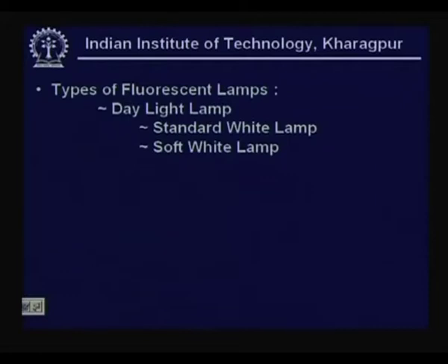Now, with this in mind, we have the fluorescent lamps which are quite often used, enabled by the utilization of mercury vapor discharge, which had a low utilization factor compared to sodium vapor but good color rendering, and that is how they have stayed on as far as interior lighting goes.